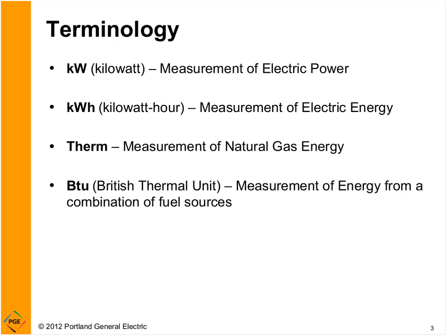So background. Wanted to touch on some main terminology that we're going to be using today. Kilowatts is a measure of electric power. Oftentimes it's an instantaneous reading. If you see kW on your utility bill, however, it's the average highest 30-minute kW demand that you've seen for that month. And I should take a step back and say that most of the comments I'm going to have today, most of the specifics I'm going to delve into, are going to be purely focused on, for the most part, PGE customers and Northwest customers in general. Your mileage may vary, your rates may be different in other jurisdictions.